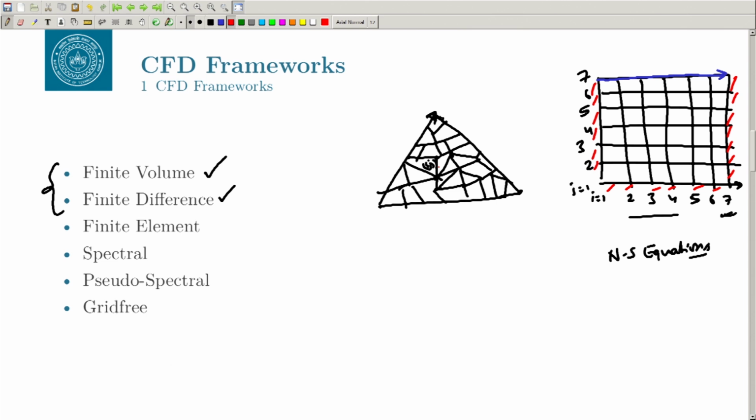It is very difficult to define because this grid is unstructured, in the sense that there is no proper structure present there. All you know is that okay, I have got this cell, okay, let us say this is a cell, and for every cell edge face I have got the left cell and right cell, okay. This is left cell and right cell, left cell and right cell, left cell and right cell, right, and this is true for every cell. You can take this cell here also, you have this on both the sides and so on and so forth, right.